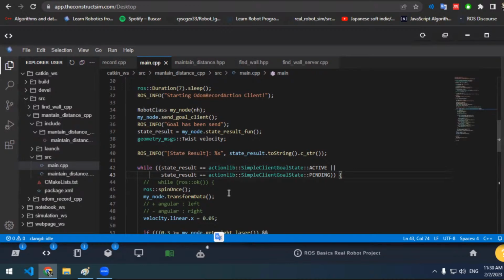But for moving forward, I'm not saying this is the wrong way to do it, but maybe this other way you'll find a little easier, especially to not have to keep track of how many ROS spin onces you have. You can do a main function at the bottom where you call your class, and then you spin. There's another method called spin, instead of spin once, that just continues to do it. So maybe it would be a good idea to see how you can restructure. I'm not saying do it, because this is perfect too.